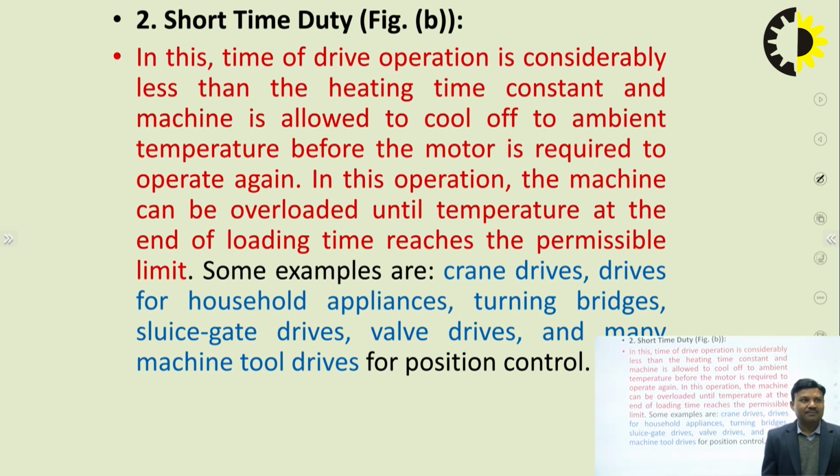In short time duty, the time of drive operation is considerably less than the heating time constant, and the machine is allowed to cool down to ambient temperature before the motor is required to operate again. In this operation, the machine can be overloaded until the temperature at the end of the loading time reaches the permissible limit. Some examples are crane drives, drives for household appliances, turning bridges, sluice gate drives, valve drives, and many machine tools.